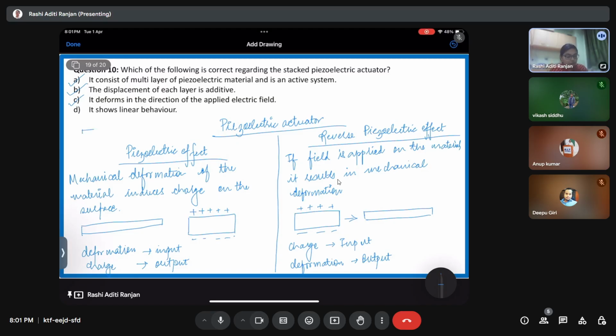Because in fluid, if you know, we talk about viscosity, where the fluid is divided into multiple layers, and there is a relative slipping between the layers, which causes the dissipation of the energy, right? In case of solid, that happens if I keep it on a surface and then apply a force, friction is going to dissipate the energy. While in case of fluids, there is slipping of one layer on the other, which results in the change of the energy.